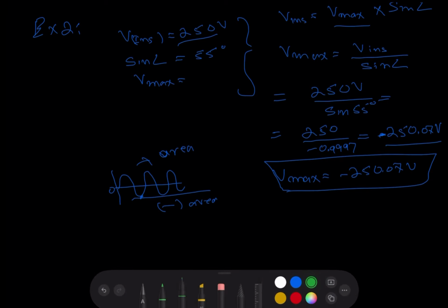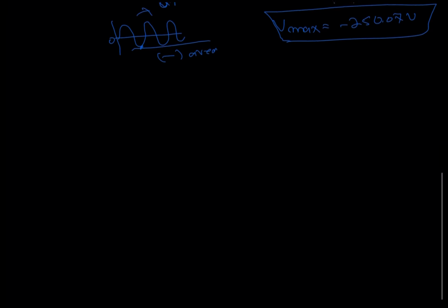Alright, moving on to the next example, number 3. Example number 3 is a sine wave has a maximum voltage of 250 volts. So V max is 250 volts. At what angle of rotation will the voltage reach 85?